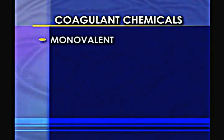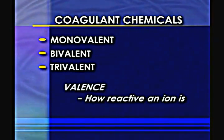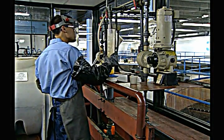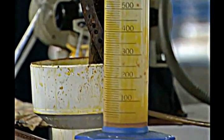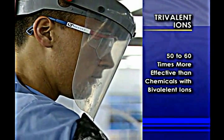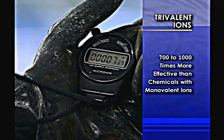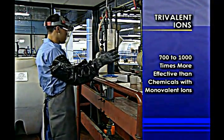Coagulant chemicals are typically monovalent, bivalent, or trivalent. Valence describes how reactive an ion is. Trivalent ions, such as aluminum or iron, have more positive charges and more sites to bind to negatively charged particles. As a result, they are 50 to 60 times more effective than chemicals with bivalent ions and 700 to 1,000 times more effective than chemicals with monovalent ions.